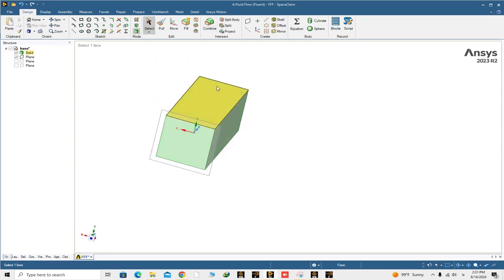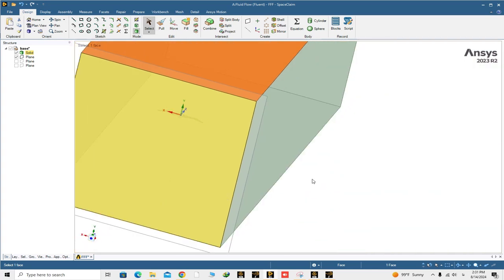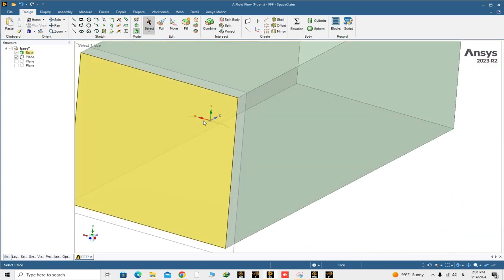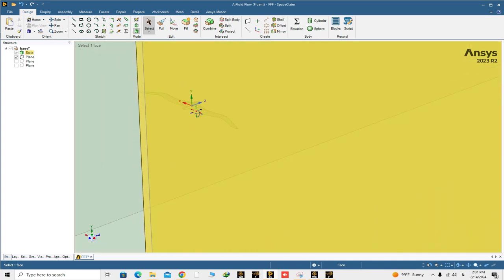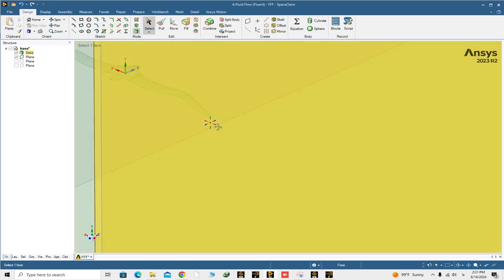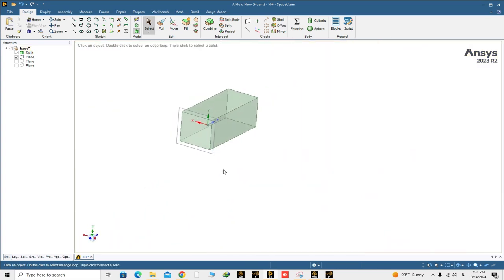If you click on one of the surfaces and see it transparently, you can see the flying bird solid is removed from the whole domain and only the walls of the bird remain. Okay, so everything that was needed for generating the geometry is done, and now we can close SpaceClaim and go for ANSYS Meshing.